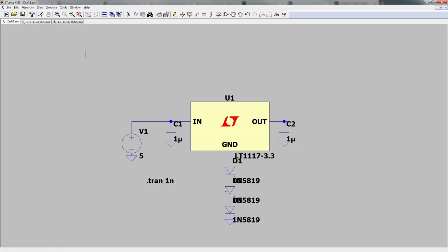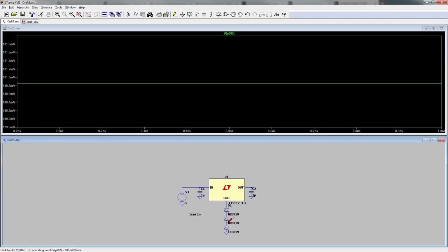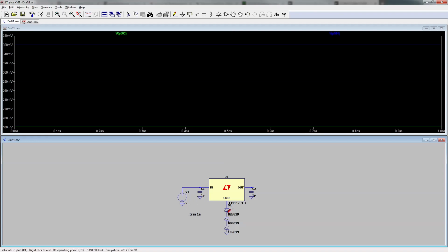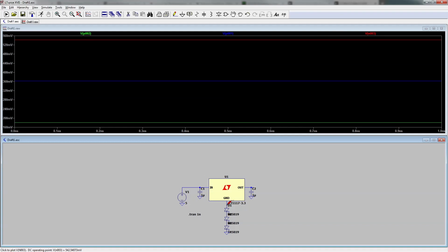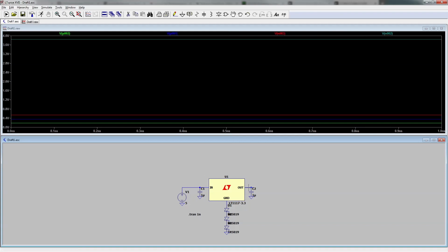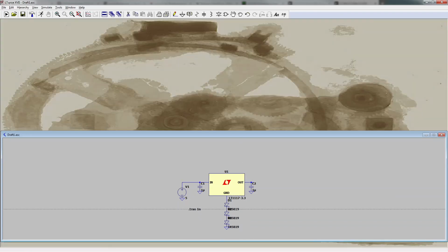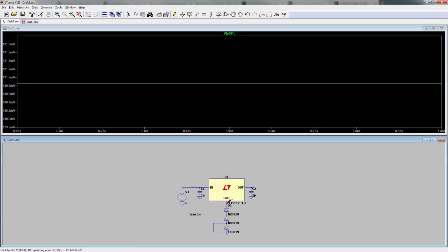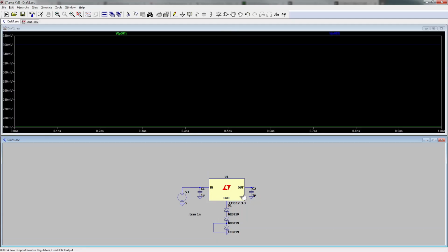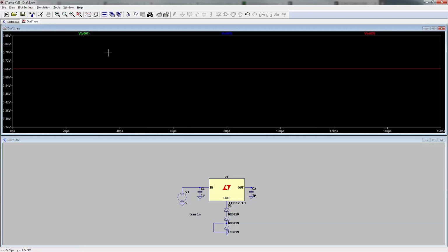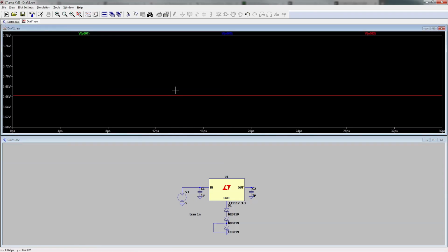So now we have 3. So let's see now, the first diode actually has 180 millivolts, the second has 360 millivolts, the third has 540 millivolts. So the final output is at 3.85 volts. If I do this again, but I short, I don't know, one of these. Now this point is 180, this is 360, and the output has fallen to 3.66.